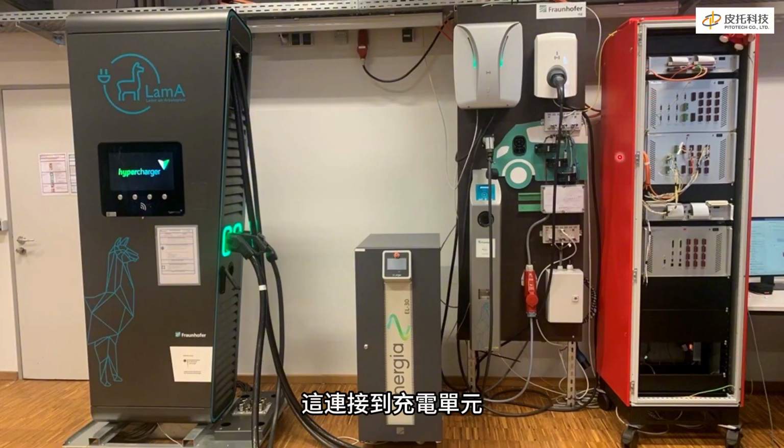This is connected to the charging unit via our emulated car, and it starts here with our CCS inlet, which makes the connection to the power amplifier on the bottom, and also connects the CP and PP contact and all the other contacts via the HIL Connect and via the board for the higher level communication, which establishes the Ethernet communication for ISO 15118.